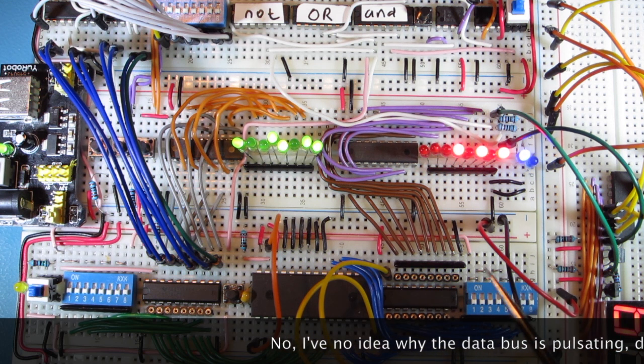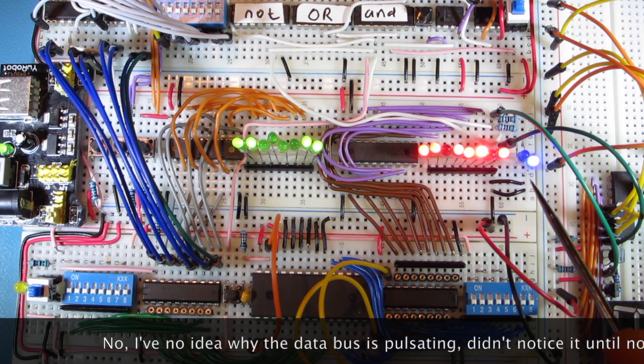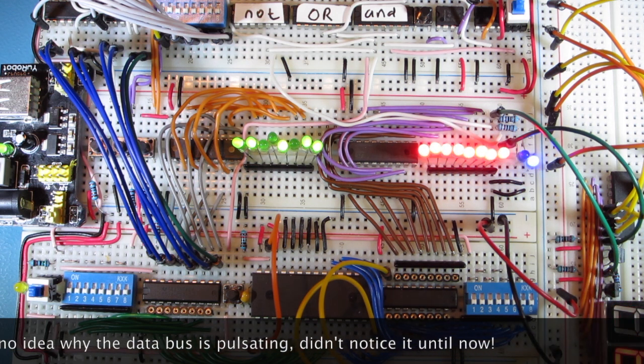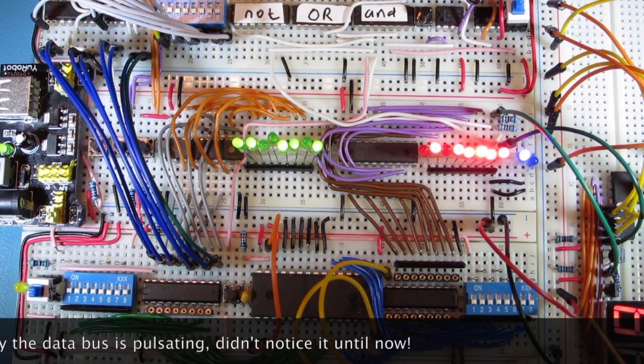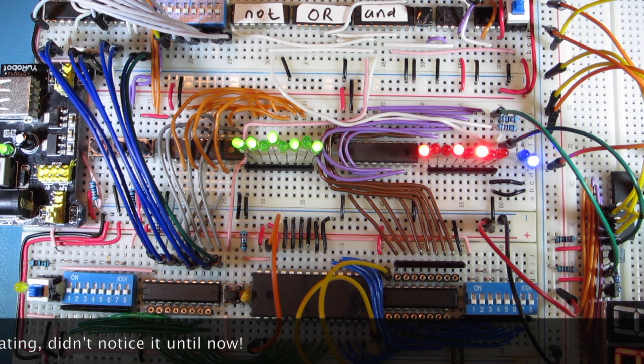I may want to trigger something on the rising edge of the clock and then trigger something else when the clock falls off back down to zero, and you can do that with an inverted clock. Whether or not I'm going to do that or not, I don't know at this stage, but it's there in case I do.